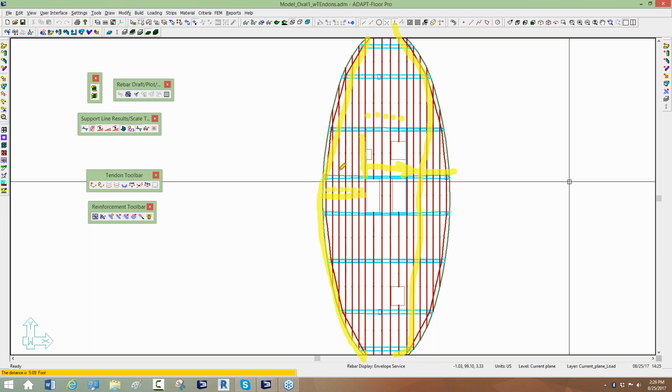So I'm not adding cables, I'm not having to track both number of cables and spacing, which happens a lot of times if you use mapping. You have to know both in order to transfer the final design from this program to your drawings. So I keep my spacing consistent, and then I'm just worrying about the number of strands. So that's how this has been modeled.